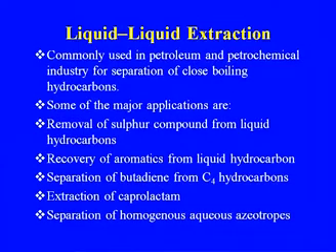Liquid extraction is again very commonly used in the petroleum and petrochemical industry for separation of close boiling hydrocarbons. Some of the major applications of liquid extraction are removal of sulfur compounds from liquid hydrocarbons, recovery of aromatics from liquid hydrocarbons, separation of butadiene from C4 hydrocarbons, because here also we have the same problem of close boiling point components, separation of caprolactam, and separation of homogeneous aqueous azeotropes.